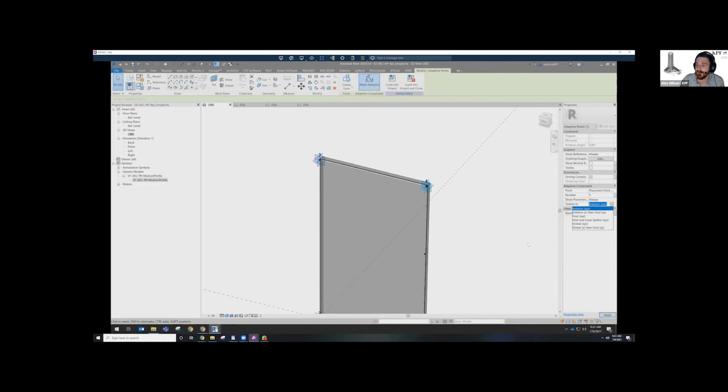We sent these files to Autodesk. They've confirmed that is a rare case of Revit not performing as expected. Basically, adaptive panels can be slightly problematic. So, building in a parameter to allow for the rotate. What we ended up doing in that example is we had, I think it was like 6 or 7 panels where the profile sweep at the back of the panel mirrored itself to the outside. So the way we got around that is we just built an instance parameter which flipped the profile.